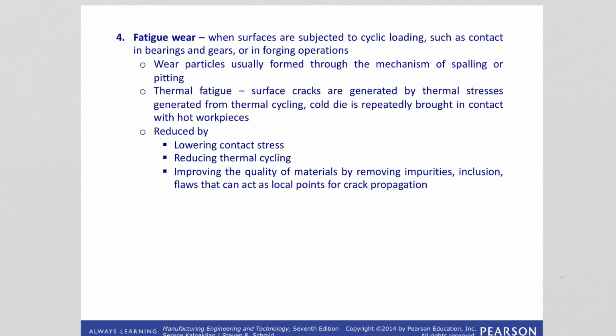And how can we therefore reduce the fatigue wear? We can lower contact stresses, we can reduce thermal cycling, or we can improve the quality of materials by removing impurities, inclusions, or other flaws, because they can act as nucleation points for the formation of cracks, and then they will keep propagating under the stress conditions.